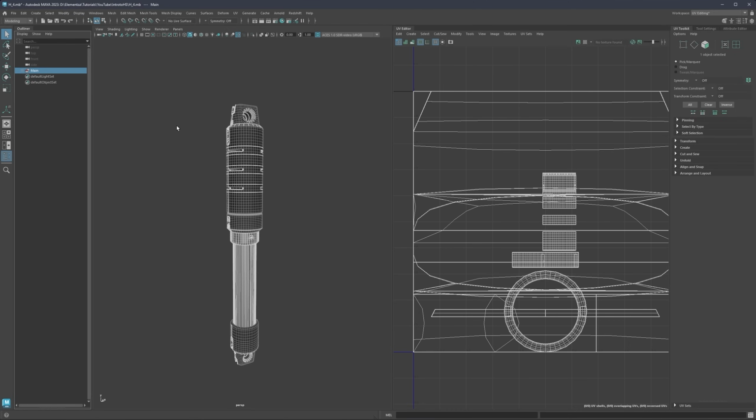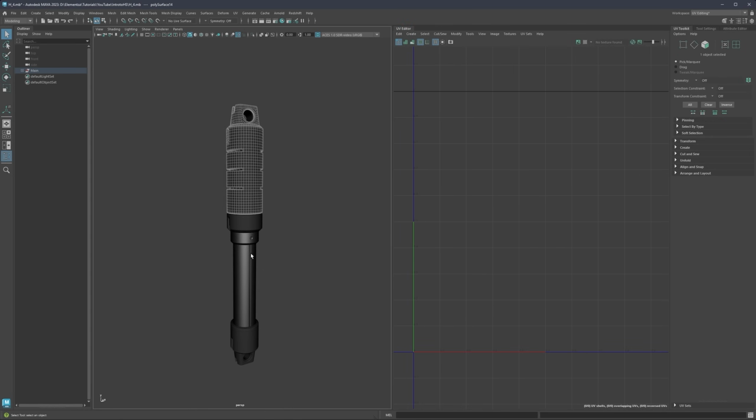And also you notice when the group is selected that here in our UV editor we already have some UVs. So in order to have a clean slate, we can just go here to edit and delete everything that we have, and we're just going to create brand new UVs from scratch. Alternatively, you can go here under UV, and then under delete UVs as well. So it doesn't matter which one you use.